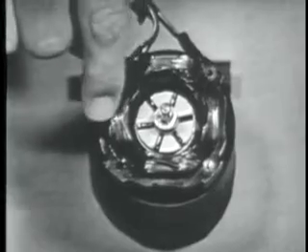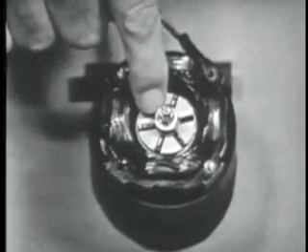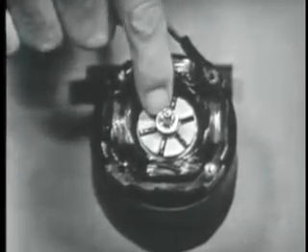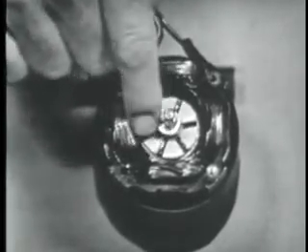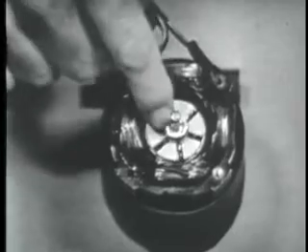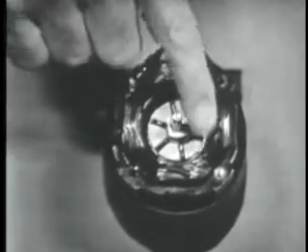Okay, so the rotating magnetic field induces a voltage into the conductors of the rotor, causing it to become an electromagnet. It exhibits a north and a south pole. The rotor turns at some speed determined by the load, both internal and external load. The difference in speed between the rotor and the magnetic field is called slippage.